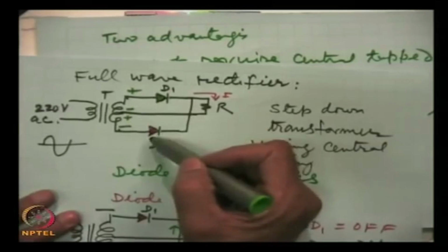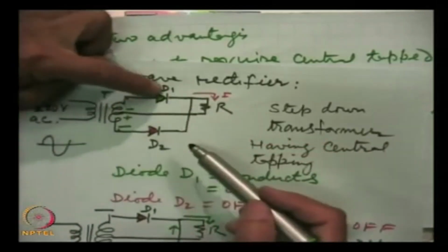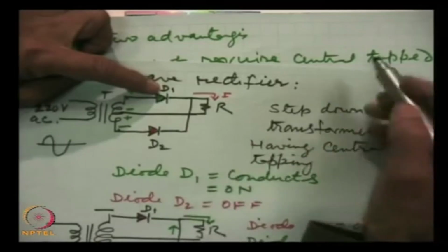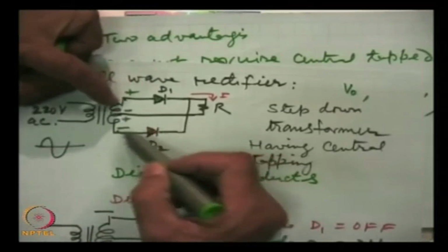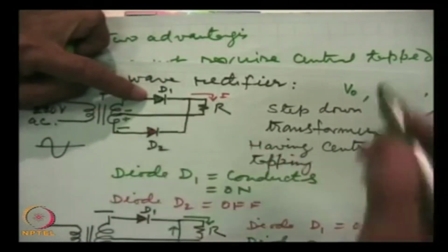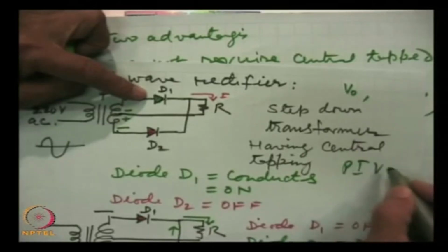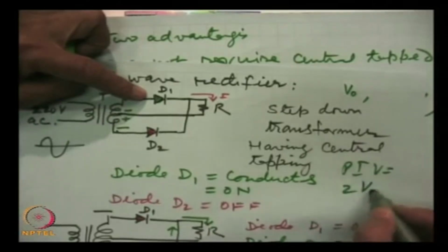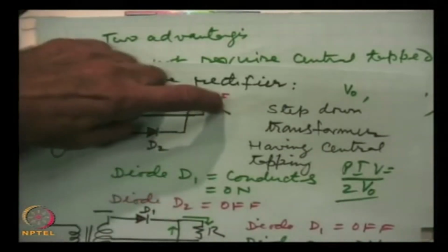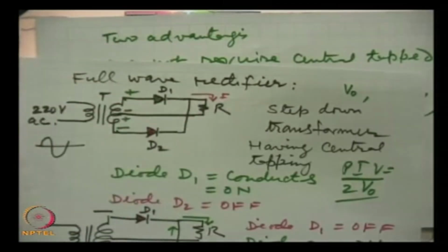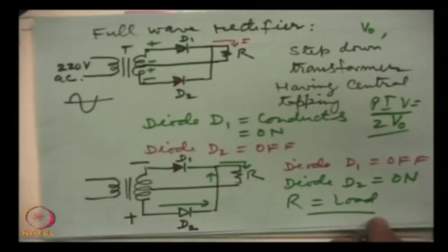In this case, for example, when this diode is not conducting, the available output is V0, but the total voltage will be dropped across the non-conducting diode. So, PIV in this case is double that available voltage. If we get 5 volts here, then the peak inverse voltage in a full wave rectifier will be 10 volts. The diodes which have a higher value of PIV are more expensive.